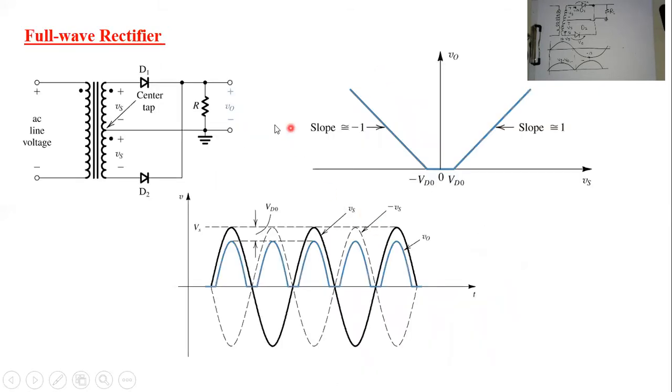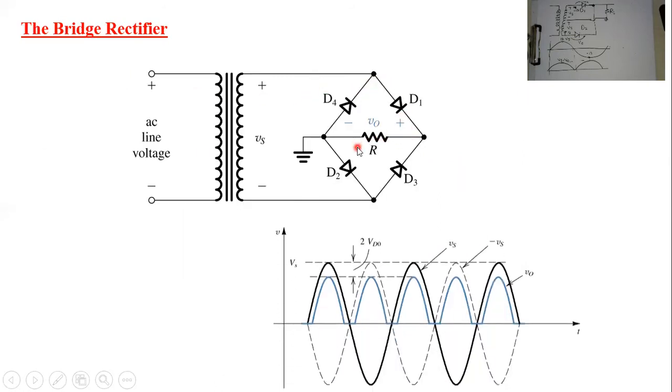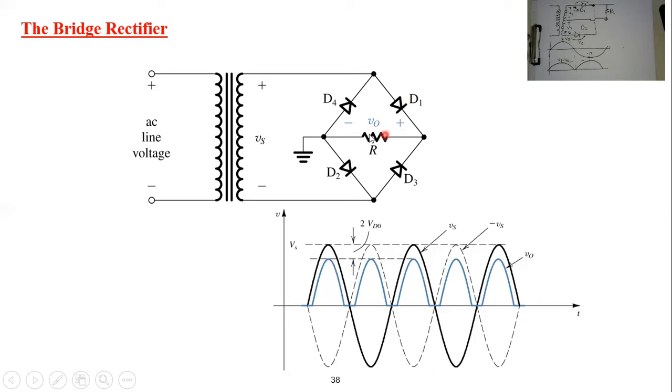In the previous scenario, you have only one diode in your path between the source and the load. However, herein you have two diodes in your path between the source and the load. That's why the voltage drop here is greater. This is what's called the bridge. It's very famous, and it's usually used in many applications related to motor operations and all this stuff. So this is one of the interesting applications where a diode can play an important role.